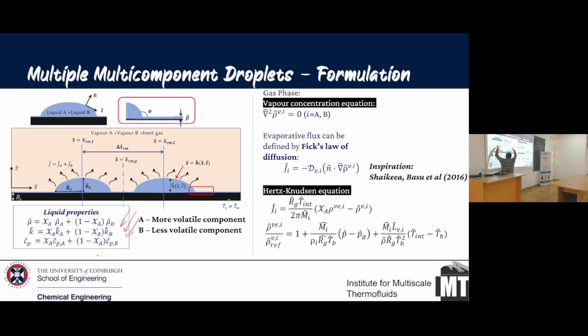So you need to have a combined system. So you need to actually evaluate what is happening in the vapor phase. So while we do lubrication approximation here, we are also considering the vapor phase in this case. So this is a step up from what we have done before. Previously, when we looked at films, we were just looking at the film and the dynamics of the film. We almost ignored what is happening in the vapor phase.